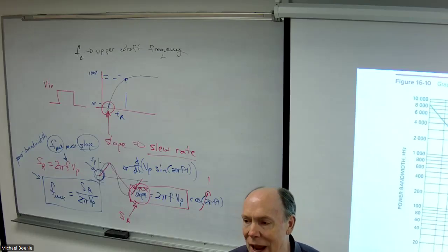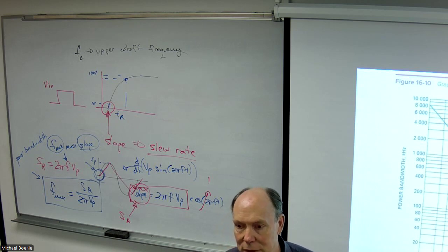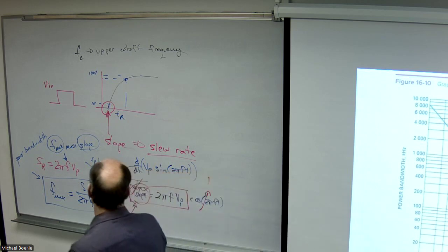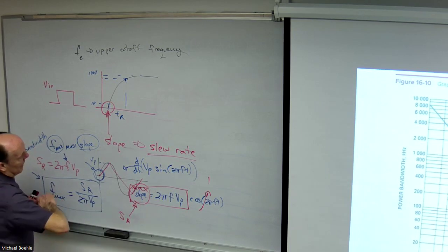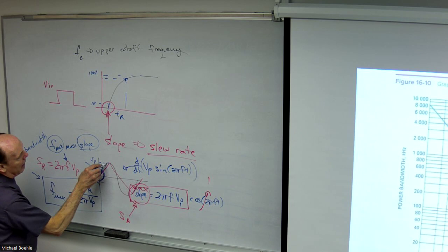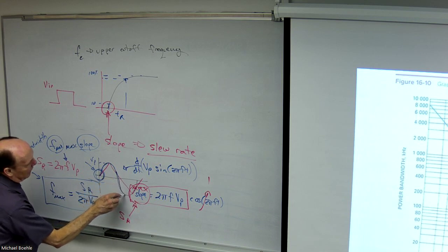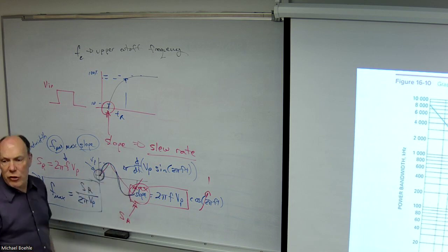Before you get to the triangle shape, you start to distort the sine wave. Maybe here it's trying to keep up. Can't quite. The higher slew rate is keeping up until it gets to there, and then it's kind of keeping up until it can't quite keep up anymore. The slew rate goes both ways. So now you get a distortion.